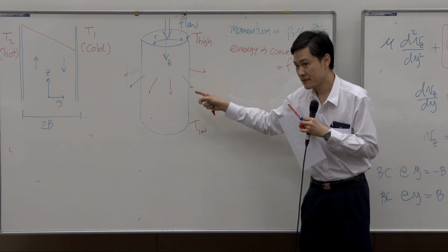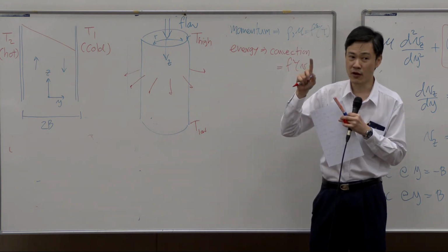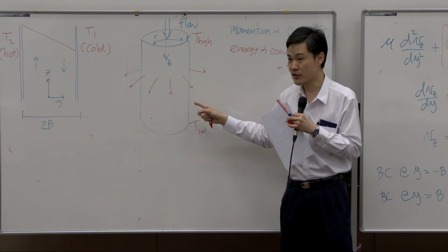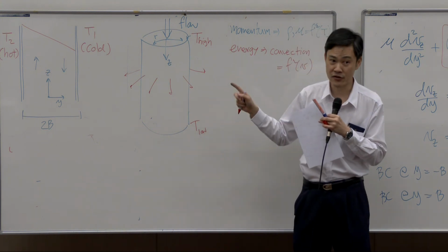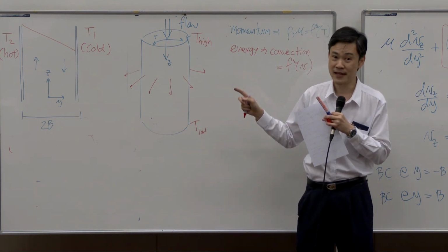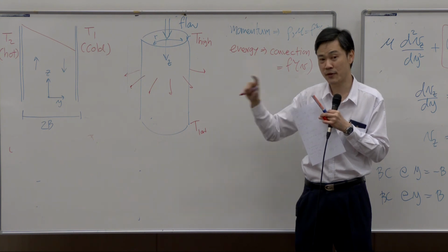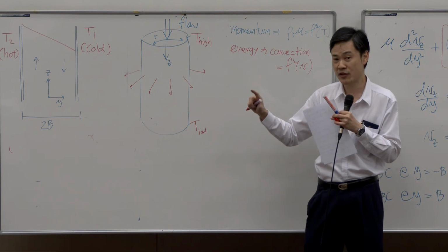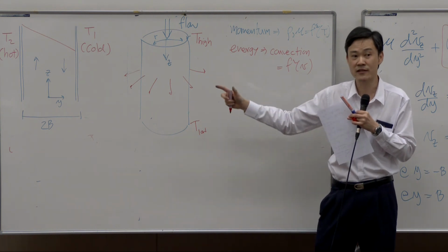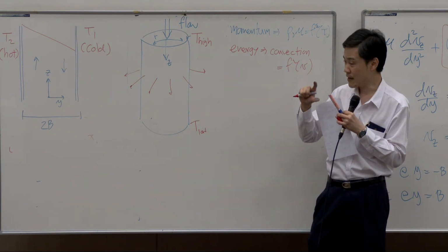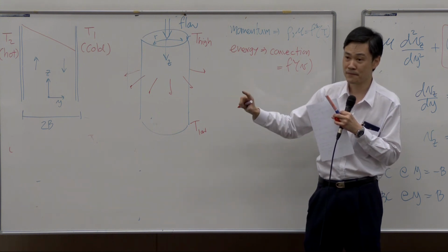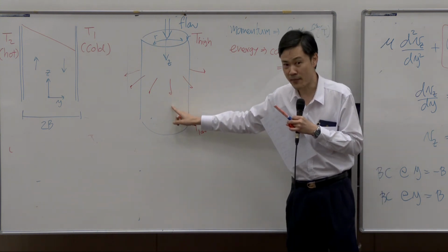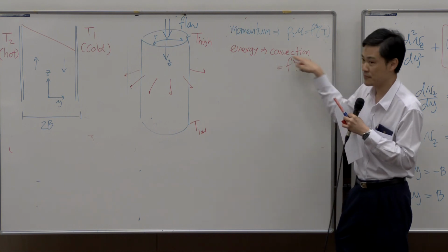In this case, you have learned from unit operation 3 that convection is more effective than conduction, right? In a heat exchanger, in order to increase heat transfer coefficient, you have to increase velocity. That's why a heat exchanger is usually operated under turbulent flow, because the velocity is higher. So now convection is dominating. That means this term is really important.